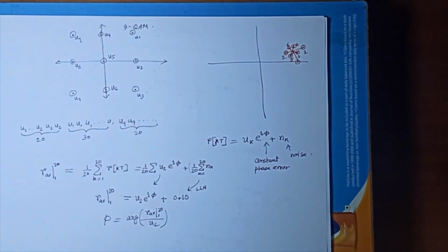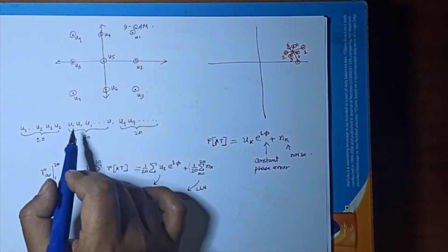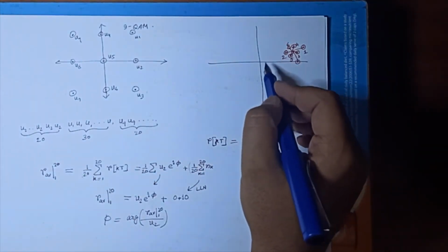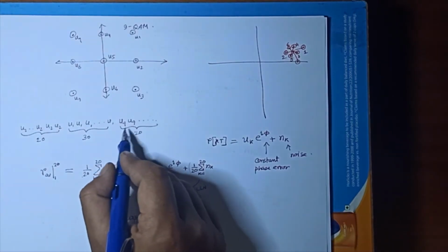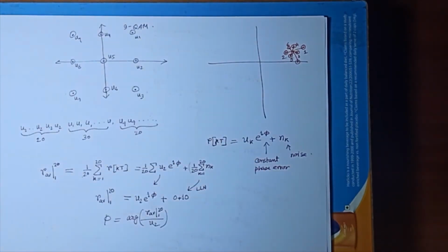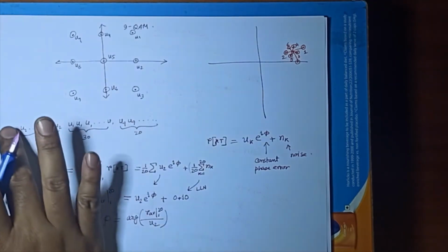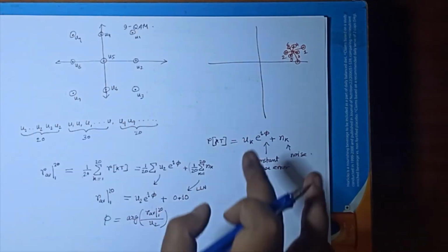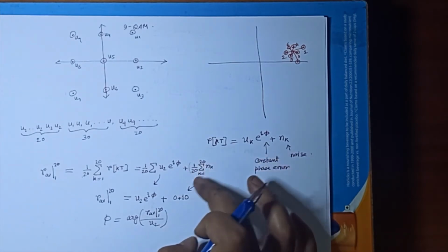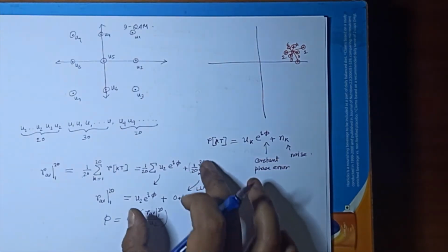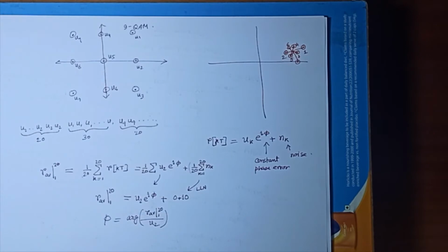Knowing this, you will get the phase. So if you want to convince more, you send u1, get the average value, send u9, get the value and compare. If they are the same, you have confidence that this is fine. Actually, sending one symbol is fine for some time, such that you can apply the law of large numbers and the noise cancels out to be 0. The sample mean becomes the expectation, which is 0. Then you can get the phase.